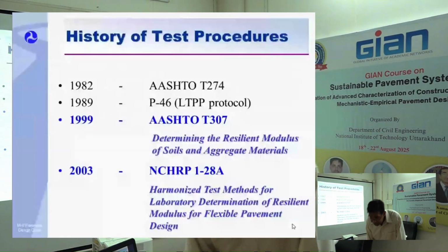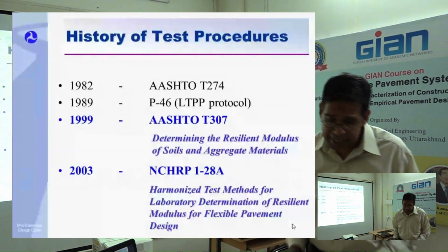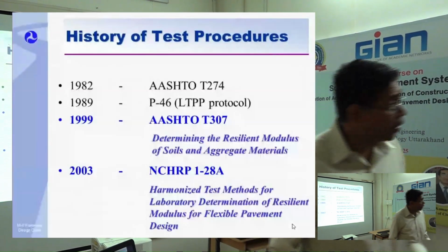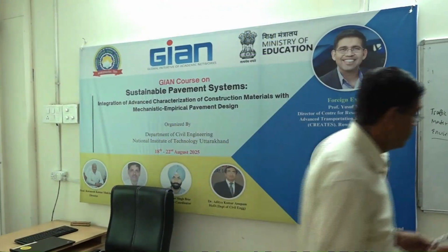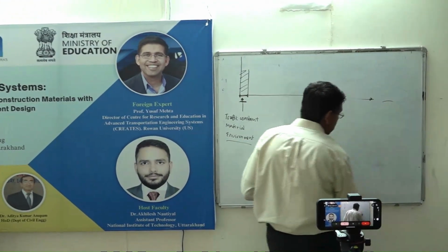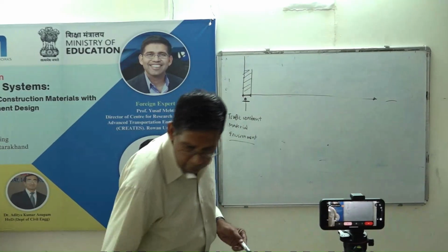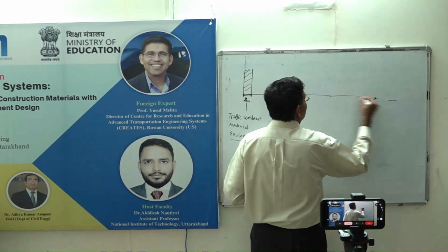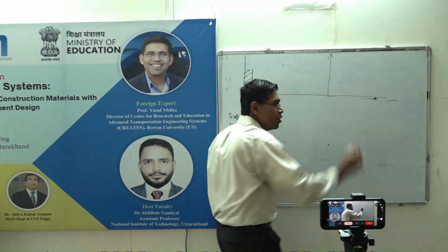Yes, correct. It is the octahedral shear stress. That's right. Tau octahedral is the same as sigma deviatoric divided by 2. So if I do a simple Mohr circle, you guys all did Mohr circle? Everybody did. It has been a couple of 100 years since I did one.